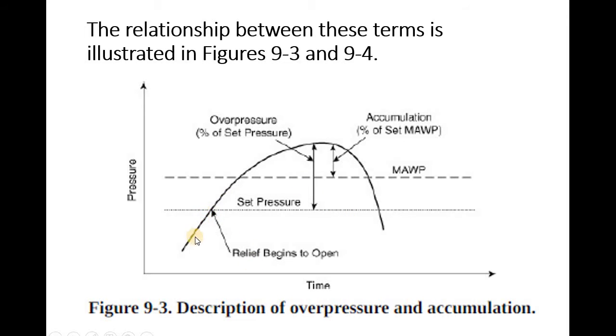So what happens here, as time goes on the pressure goes up, it reaches a certain pressure, and the relief valve opens. So what is that pressure? We call this the set pressure. So the set pressure is the pressure where the relief valve begins to open.